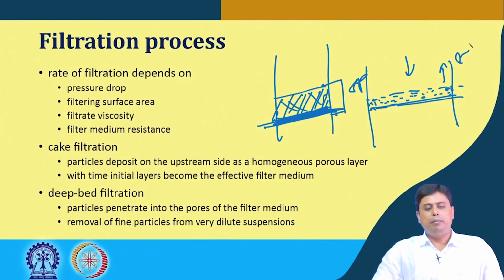In deep bed filtration, what happens is that particles penetrate into the pores of the filter media, because the filter media has certain pore sizes which are usually larger than the particles that are being removed.